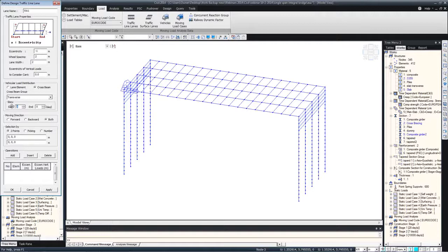This is where you enter the skew angle. So I'll enter 15 degrees and 15 degrees at the start and end of the deck. And there are different ways of selecting the reference line. Either you create a start, just click on start and end points. Okay. And click apply. So you will see the remaining area lane is generated.